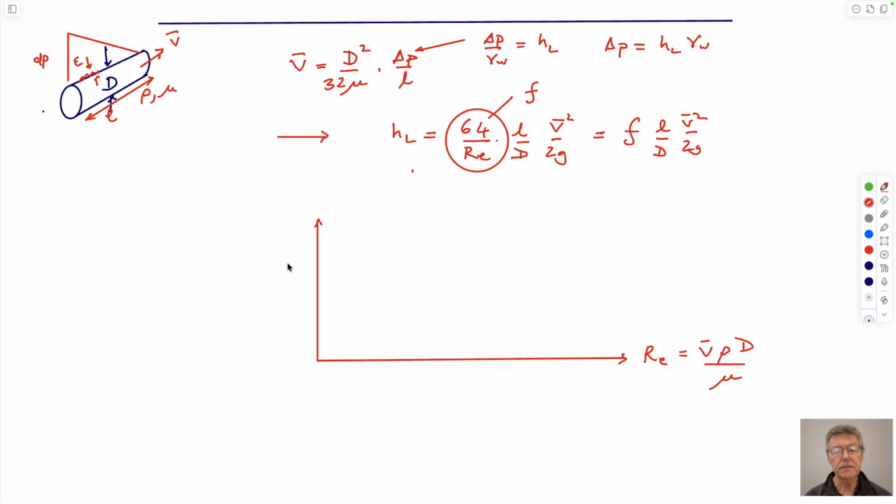I just drew this as friction factor, not to confuse things. It's a surrogate Euler number. It's kind of friction factor. The only things we're interested in are an ordinate on here which is about 2 times 10 to the 3. On one side of this, it's turbulent. The other side, it's laminar.